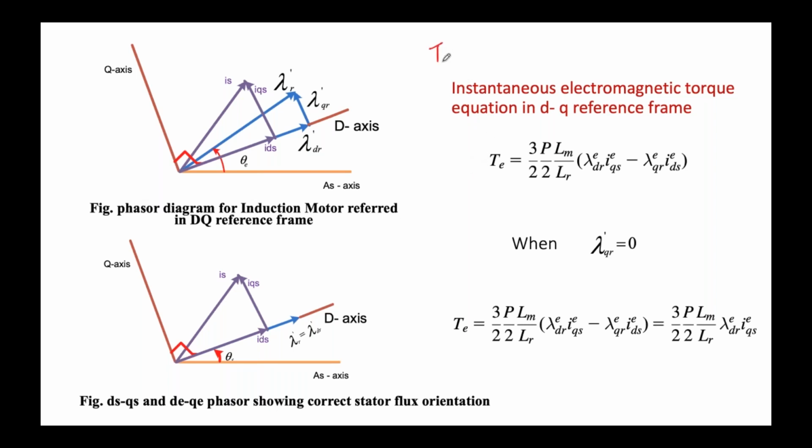Here we have already discussed that the torque is seventh order for an induction machine. If you take the seventh order expression, it will become fourth order after applying the transformation techniques. Simply by applying the transformation technique, don't think your torque equation becomes linear. Don't think it is coming in first order. Even if you apply the two-phase transformation technique, you will not get a linear expression. Your torque expression is still non-linear. It is a fourth order equation.